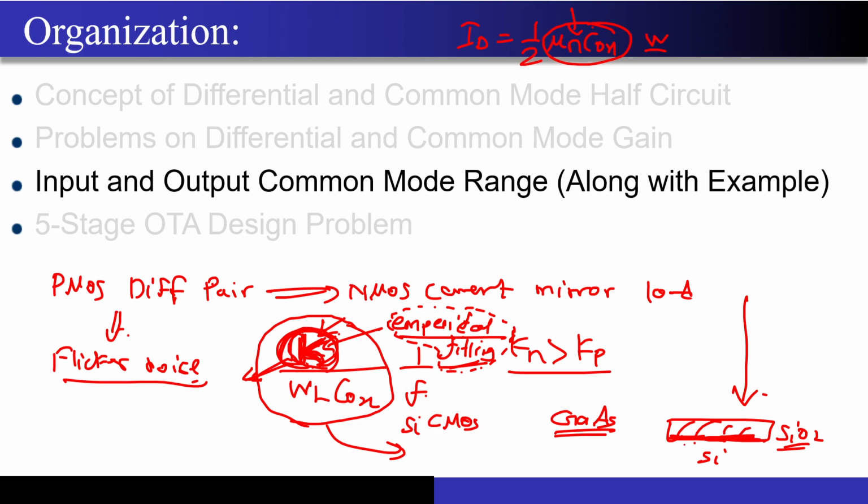And remember, mobility gets degraded because of it. I don't think this K depends on the mobility. It is actually the opposite. If there are a lot of traps or a lot of roughness at the silicon to silicon dioxide interface, your mobility can degrade, correct? Your electrons are moving with a high field. If they see such roughness, the effective velocity will be reduced because of scattering, and the mobility will degrade. So this K is a representation of this roughness. This is what you can think of intuitively.